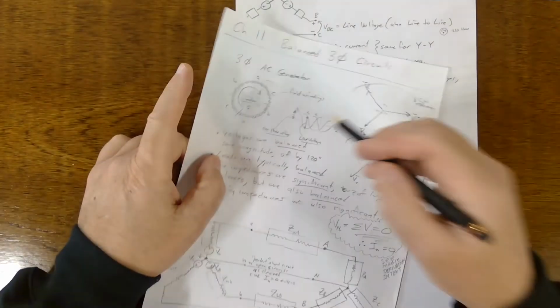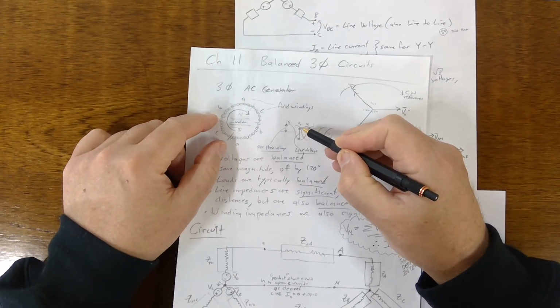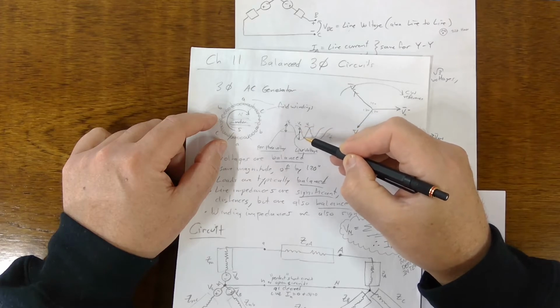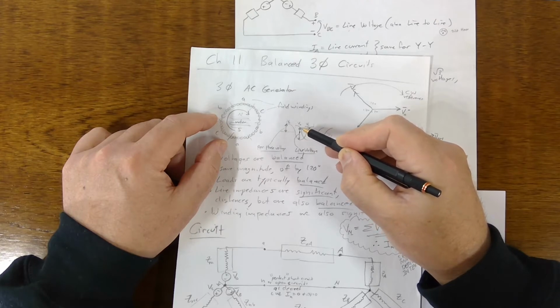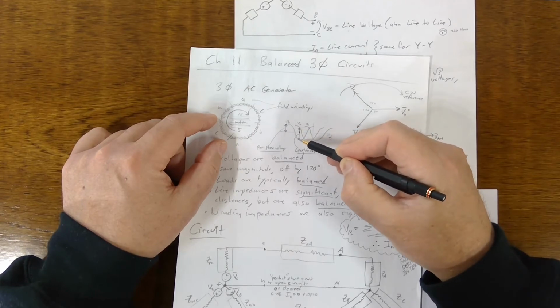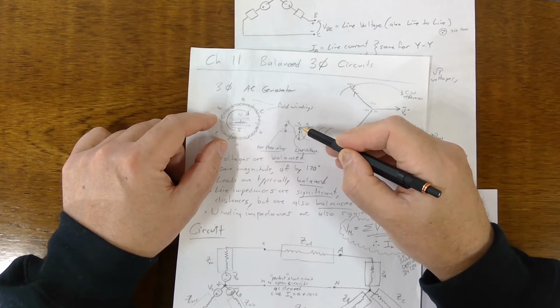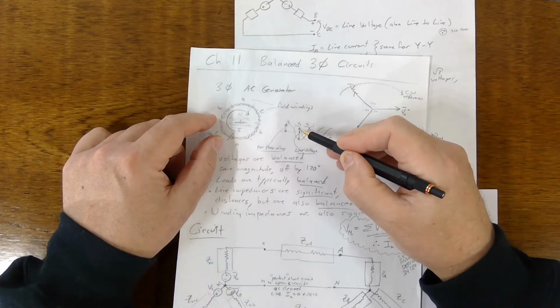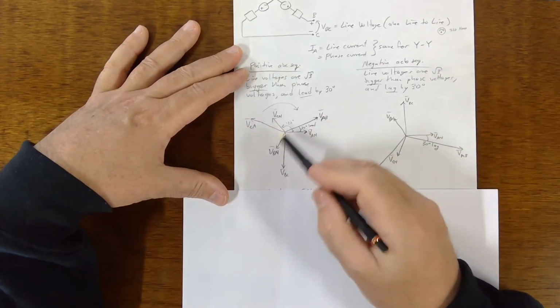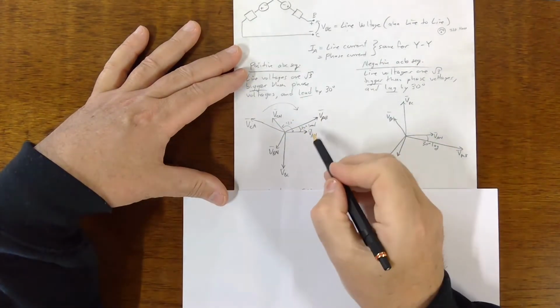I don't know if you can see that, like right here. See, there's a certain point where the VB minus VC will be 0. So that's another sine wave starting at 0. And then there's a difference in here where these guys are maxed. I guess it could be here, maybe it's here, I'm not sure. But there's a point in time along in here where VC minus VA is max. And then there's a point of time where VB minus VC is 0. So VB minus VC is just one more sine wave. So that's sort of shown in this phase diagram.